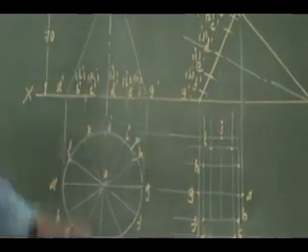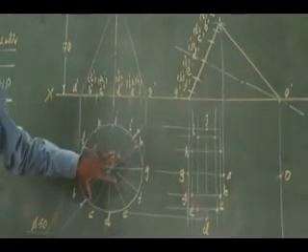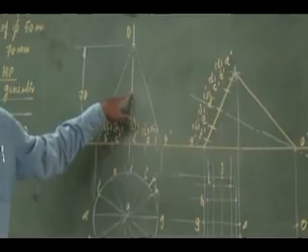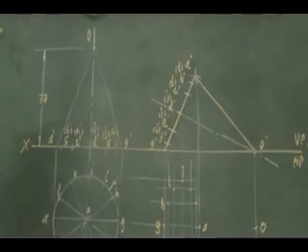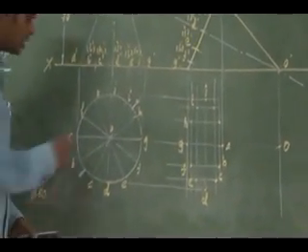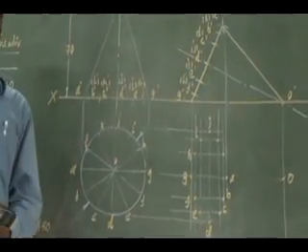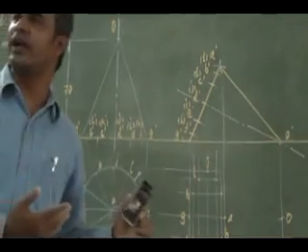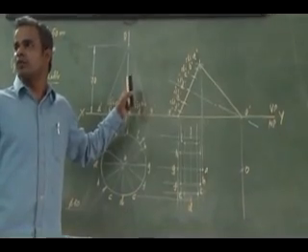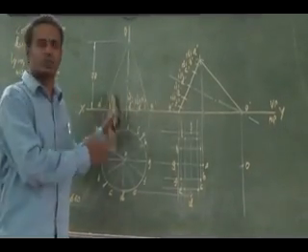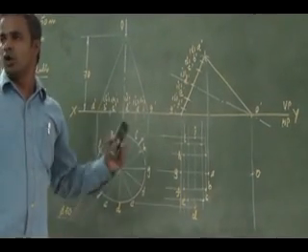The cone is lying on the ground like this, right? I have drawn the base on the ground, HP, then I have drawn the front view in a simple orientation, then I have tilted the cone. While drawing the cone, you have to mark the generator base points. In the front view, you cannot see all the 12 generators, and you should not show them. Why? A generator is a surface. Only the extreme generator alone should be shown in your cone.